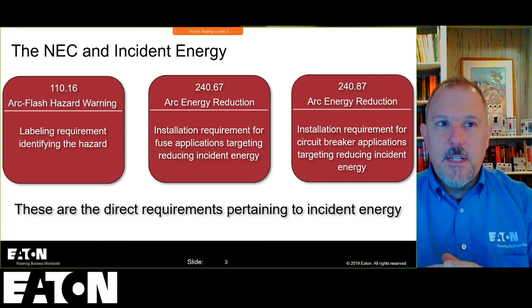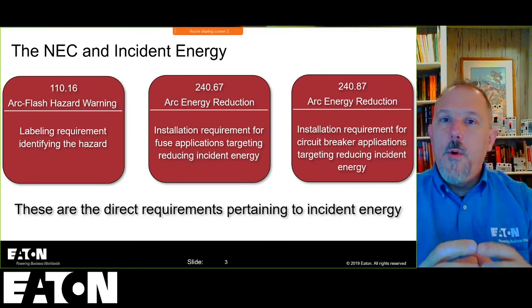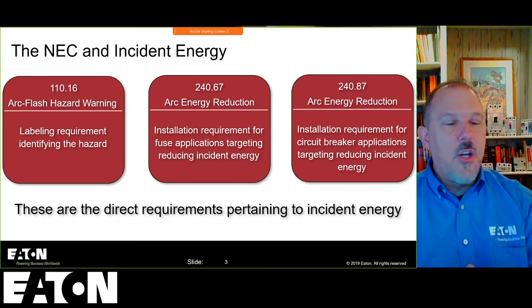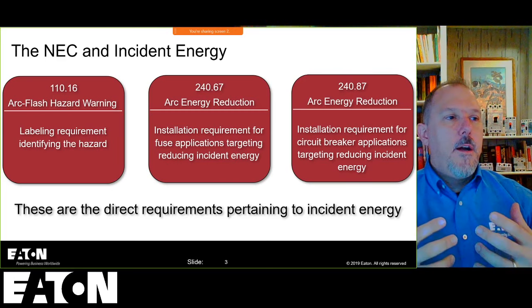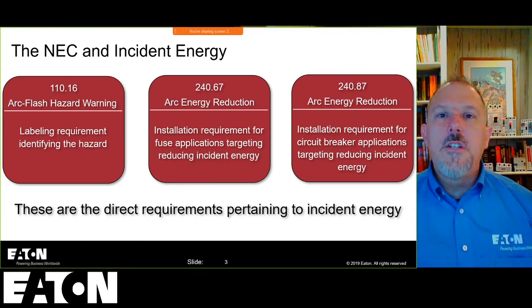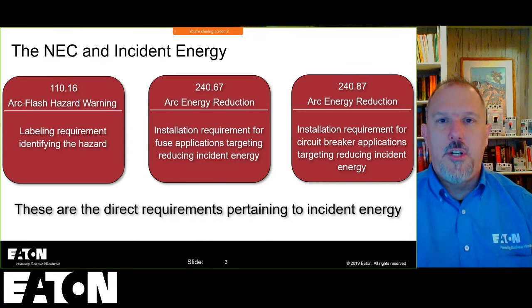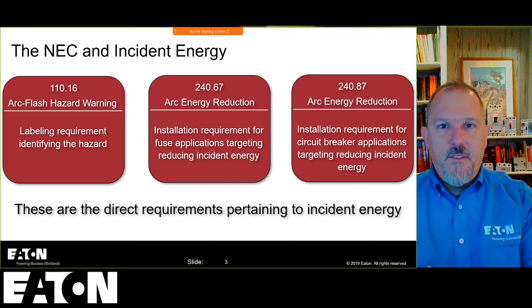So that's the first thing that happened. They went from ungrounded to grounded. Then they went from an average of 208 volts on the services to 480 volts. And what does that do? That's like turning up the pressure, baby. If I relate that to water, that's like you've got a bigger dam, right? Because voltage is pressure in the power distribution system. So you grounded it, you don't have that free first fault.